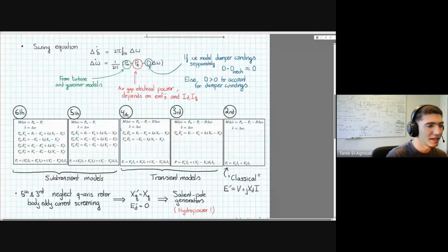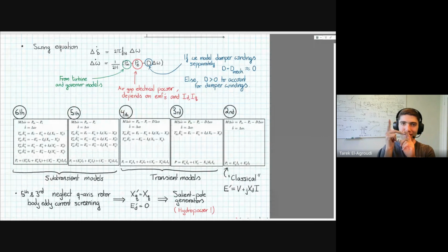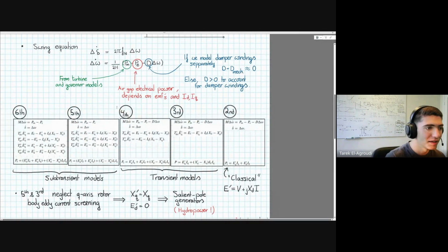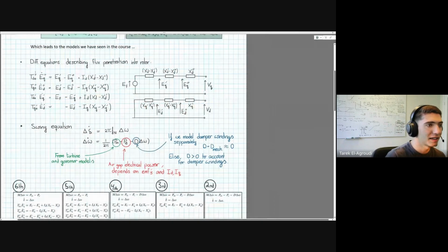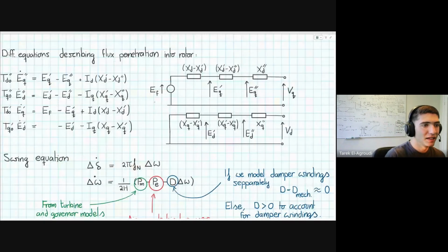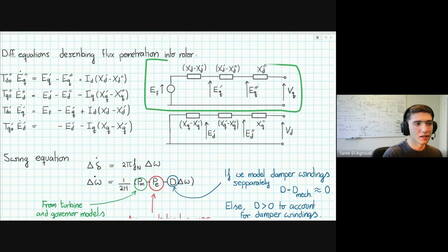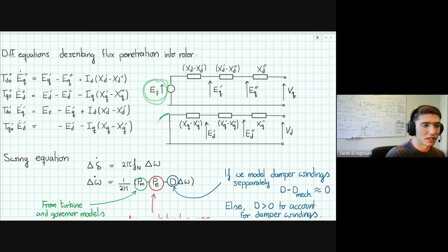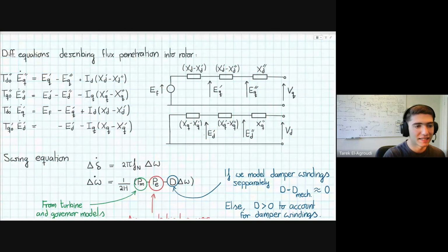It's also worth mentioning, you can put all of these different transient, subtransient and steady-state values into the same circuit diagram. And then you will get something like this. So for the q-axis, there is this field voltage, which is not there in the d-axis. But then due to these subtransient and transient reactances, you will get some sort of d-axis transient and subtransient voltages.